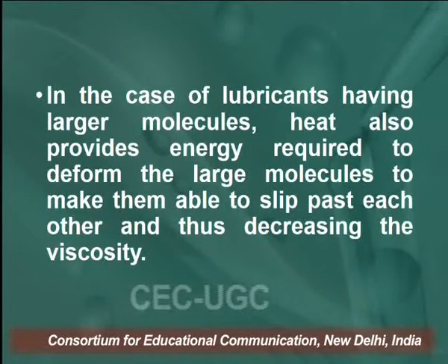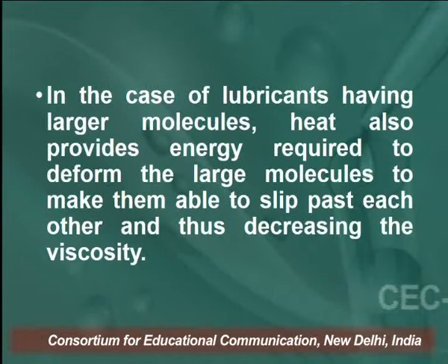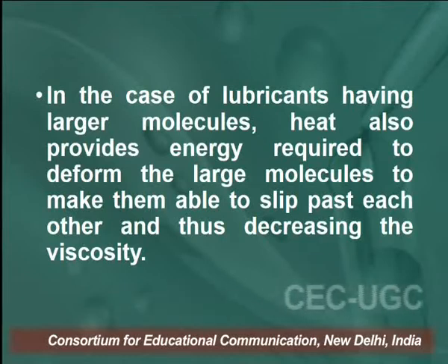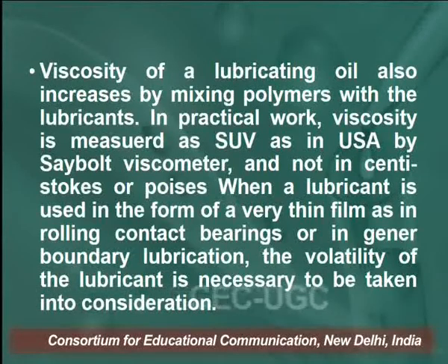In the case of lubricants having larger molecules, heat also provides the energy required to deform the large molecules to make them able to slip past each other, thus decreasing the viscosity. So, the viscosity of a lubricating oil also increases by mixing polymers with the lubricants.